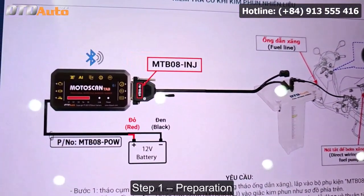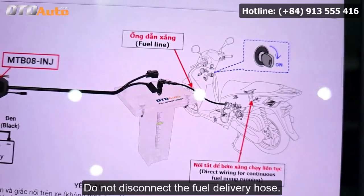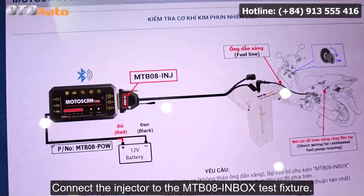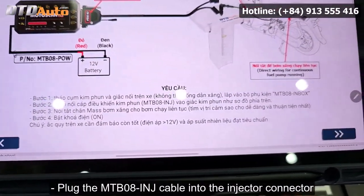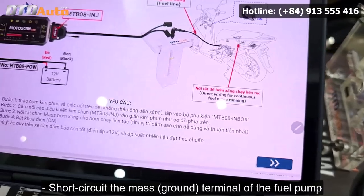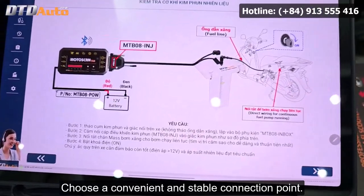Step 1. Preparation. Remove the fuel injector and its electrical connector from the vehicle. Do not disconnect the fuel delivery hose. Connect the injector to the MTB08 inbox test fixture. Plug the MTB08 INJ cable into the injector connector, as shown in the provided wiring diagram. Short-circuit the mass, ground, terminal of the fuel pump to keep it running continuously. Choose a convenient and stable connection point.